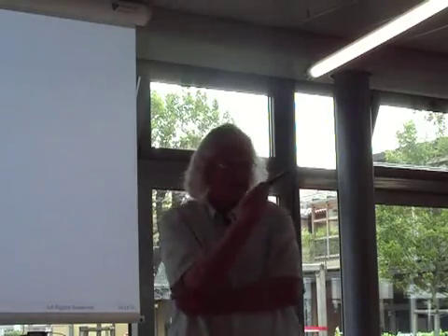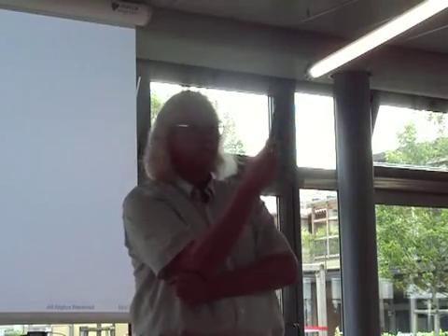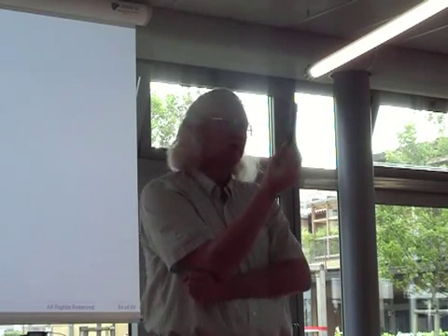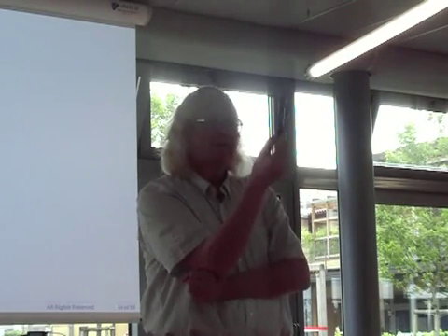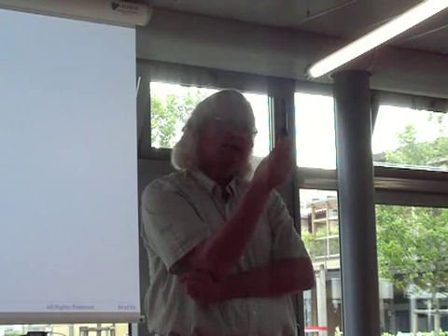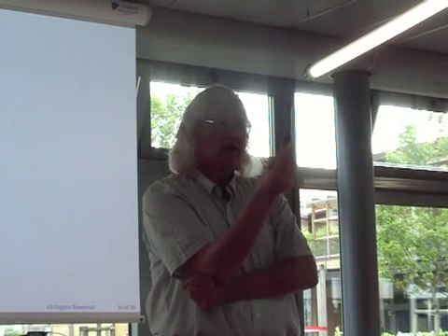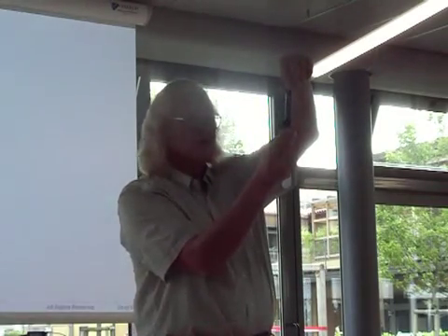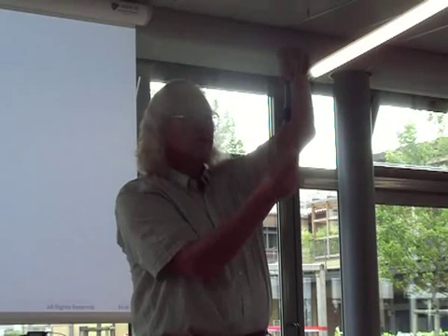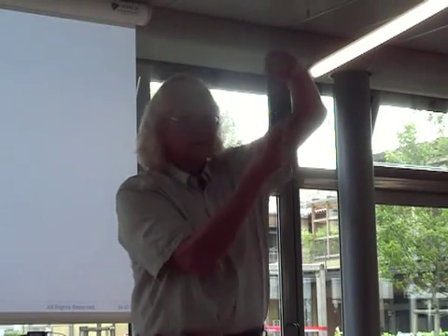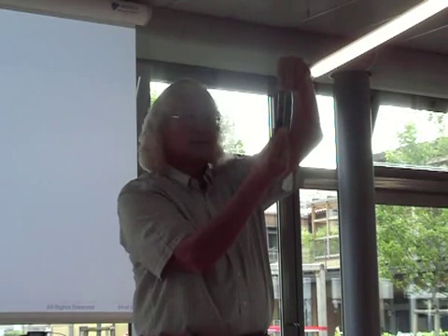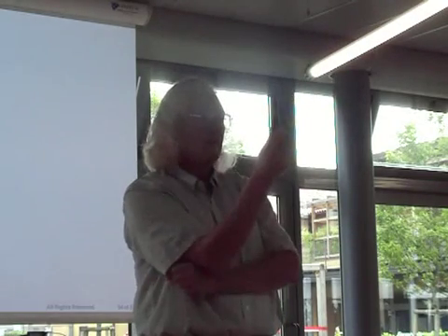Okay? We do an experiment. I load this bar, and I'm going to make the problem easy because that's what professors do. So when I see this bar, I see an area of 1. Okay? And now I'm going to load this with a force of 10. Okay? What is the stress in this bar?